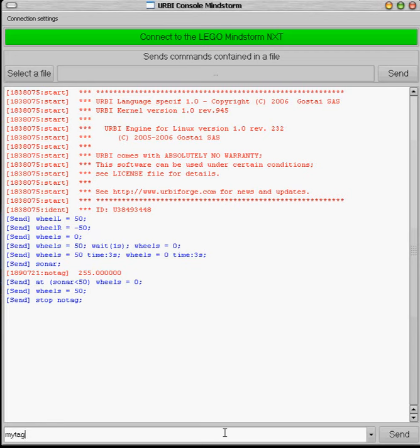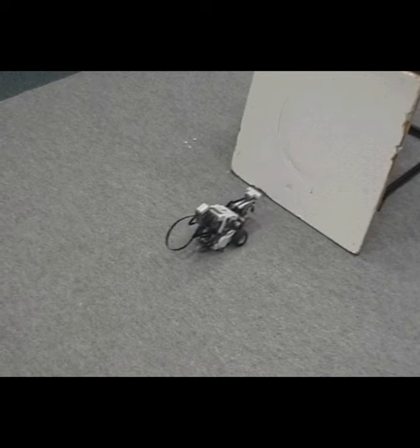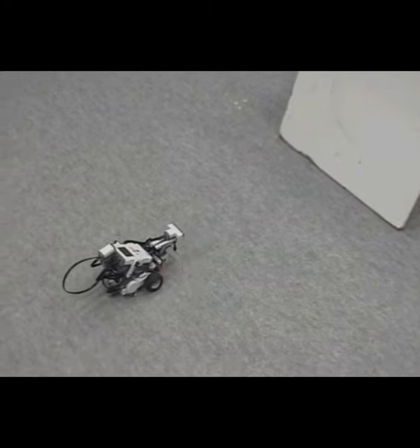Let's use the tag now, and let's make another @ which triggers when the bumper is pressed and then sets the speed to minus 50 to move backward. Here, bumper is one of the many sensors that you can read. See the complete manual for a list. To test this new @ let's move forward towards a wall. Bumper contact, and then backward.